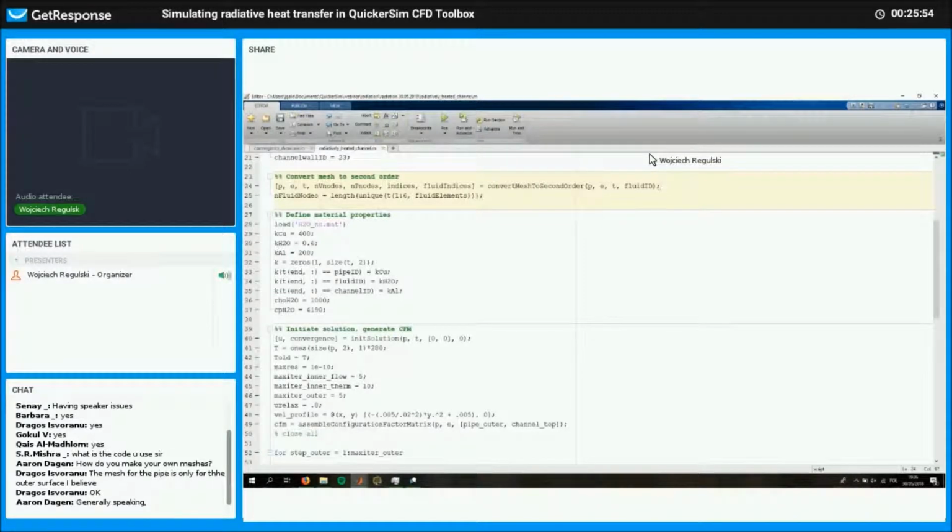It's basically a mathematical theorem which specifies the function spaces you need to choose for your approximations so that your pressure solution is unique. You don't really have to worry about that. Suffice to say that we use the second order approximation for our velocity and a first order approximation for pressure. And the n fluid nodes is just the number of fluid nodes. It's very simple.